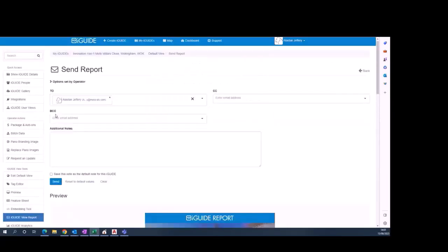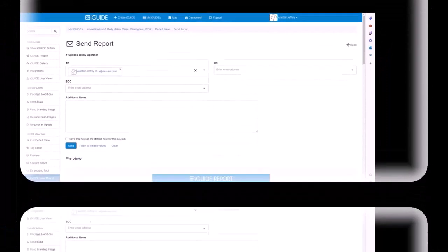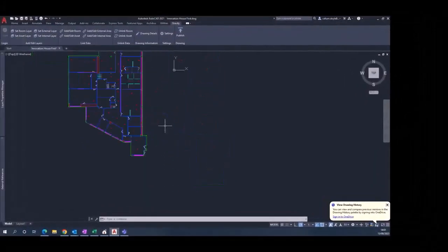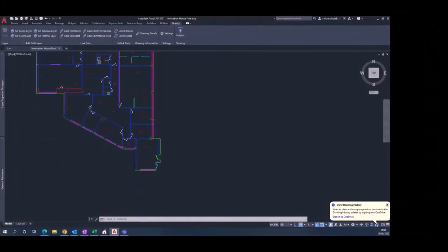Now if I switch to AutoCAD, I'm going to show you that same drawing. It's a different orientation, but you'll see it's the same thing. So this space here is the reception space. This went off in a stitch format, in a single file with all the data in one thing. What this has returned to me is a DXF file. So I've opened that in AutoCAD, saved it as a DWG, and now you can edit it as you would with any other AutoCAD drawing file.